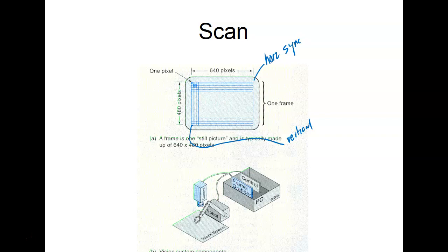In real old TVs, we actually had controls on our TV. The TV would start rolling, and you'd go, we called it vertical hold, and you'd have to adjust your TV a little bit to get back in sync. Horizontal, if it lost horizontal sync, the TV would lay over. And we had two controls on our TV.